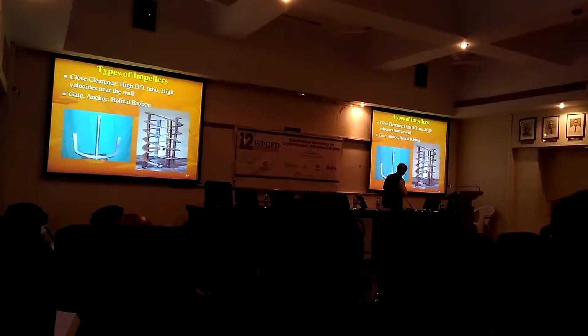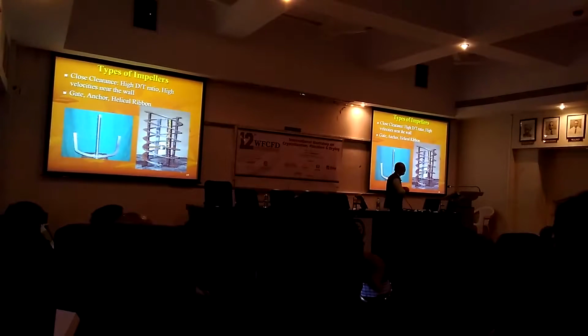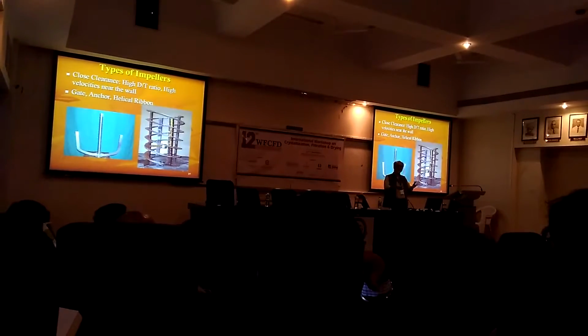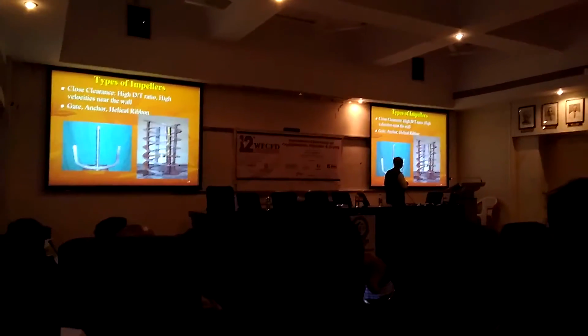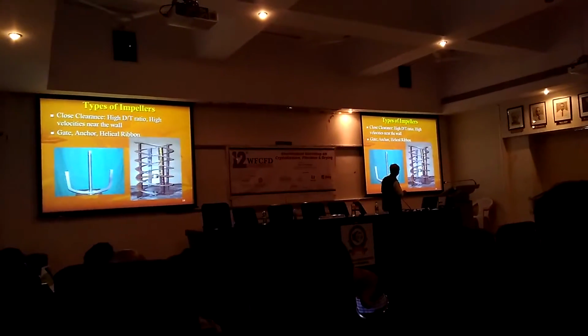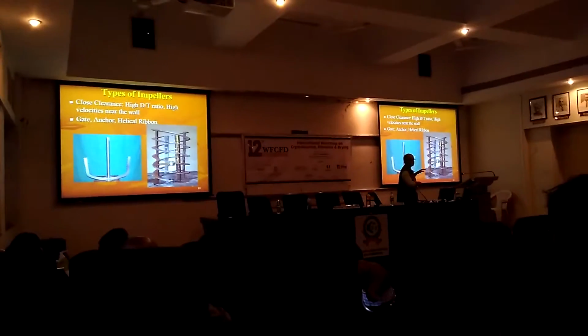So the suspension can be achieved by using 2 horizontal plates, maybe inclined plates, so you can use a combination of a pitch blade turbine and an anchor to effectively remove the bottlenecks associated with only anchor. Now this is too much of metal going in it.